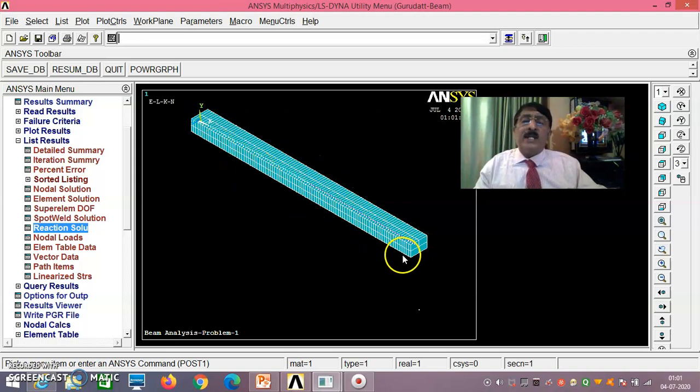Irrespective of the orientation, this bending moment and shear force diagram will be the same. But actually the maximum bending and all that, the orientation has to be proper. This we will take care of in the next session, that is session 3 on beam analysis. Up till here, the beam orientation is not at all important. Now in order to get the correct displacement due to load, you need beam orientation. That we'll do in the next session.